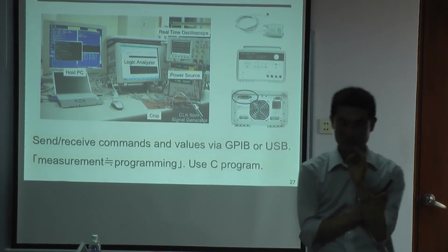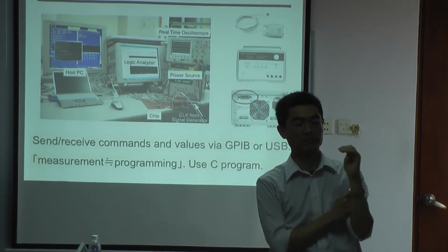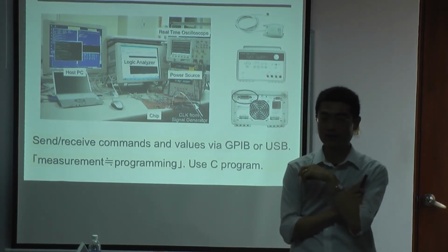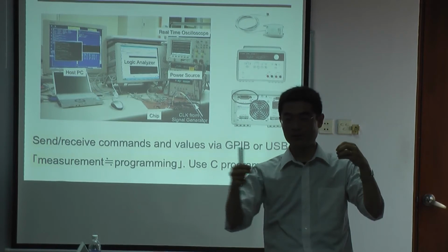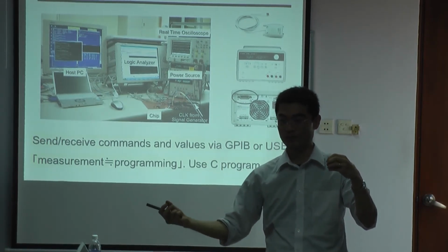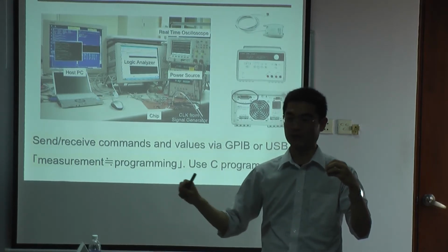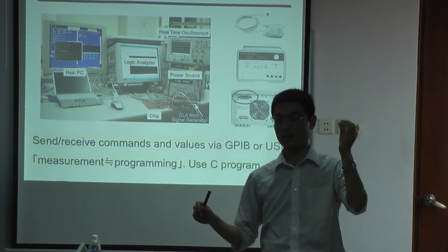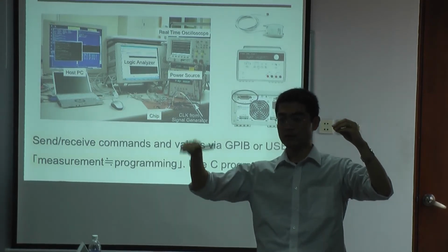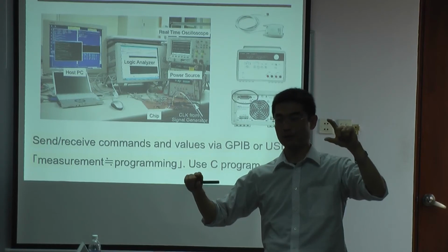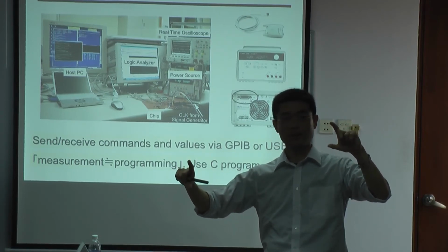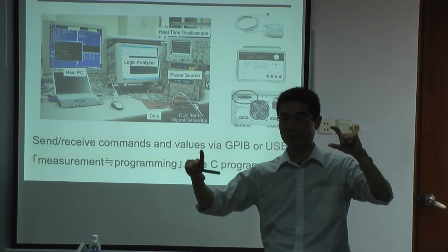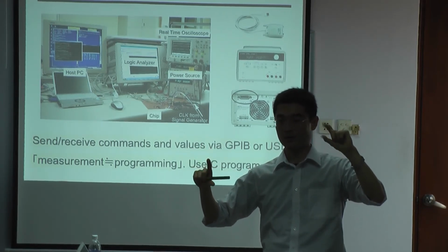Okay. Usually when you simulate, you know the output impedance from the simulator. And on the real device, you connect the output to the oscilloscope, which has a 50 ohm impedance. So the oscilloscope input impedance is always 50. Let's say you have 1 volt VDD and the output is high, then you will see the output voltage here. If the output impedance is 50 ohm, the output voltage becomes half. And from that measurement, you will see the output impedance.